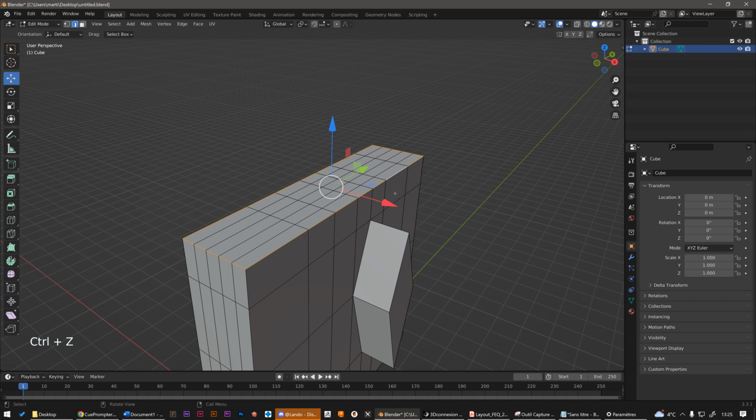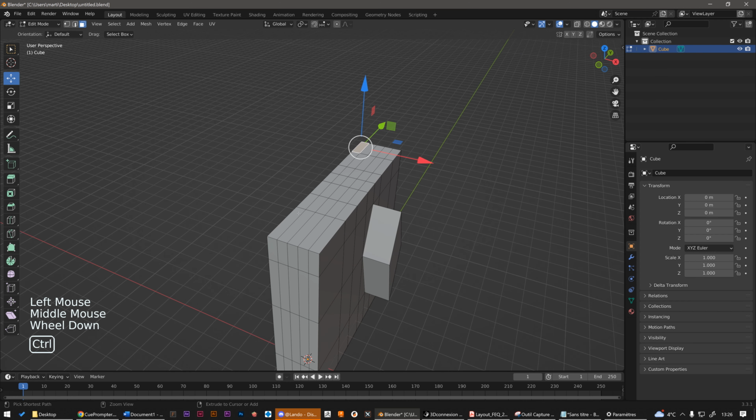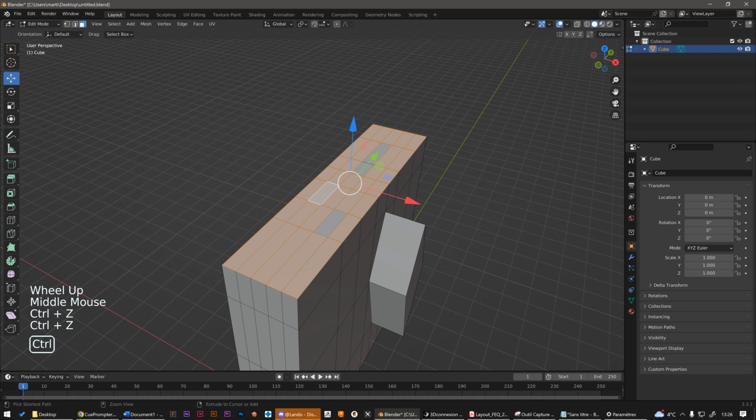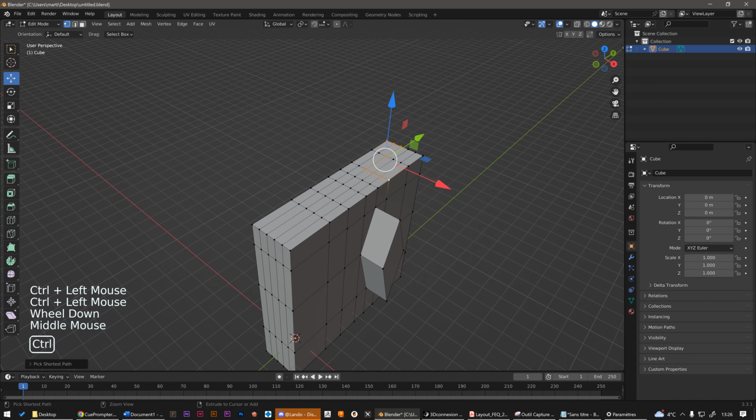And it also works with faces. So, if I select this face, then I hold the Control key and select another face, Blender allows us to quickly select several faces following the shortest path along the topology. So, there I did something a little weird, but a common trick is to draw a kind of snail. I start by selecting this side, and I complete the selection by drawing a spiral. And it's also working with vertices. You will see, this tool is very convenient for a lot of situations.